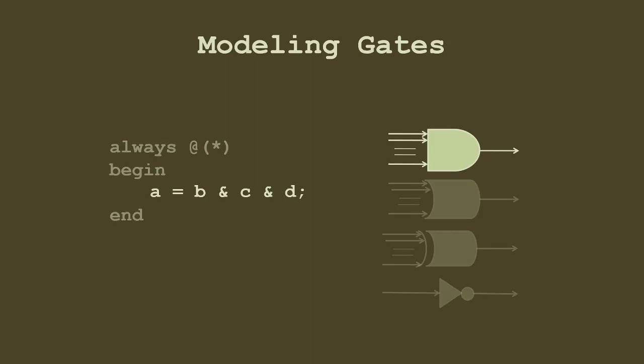So those who already know C know that in C this ampersand sign is used for AND. So in Verilog it's also used for AND. And it works in exactly the same way. It's bitwise AND by default, and if we use double AND, it will be logical AND. But normally we don't use logical AND when we are designing logic. Similarly, for OR, we'll be using this bar symbol that we use in C. For XOR, we use this cap signal, that symbol that will XOR multiple things. For NOT, we use tilde sign. So these are all bitwise operators in this case.